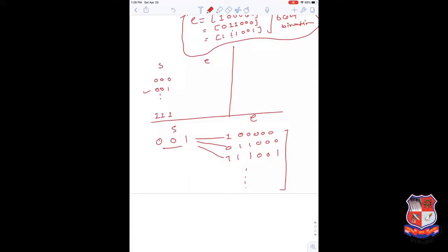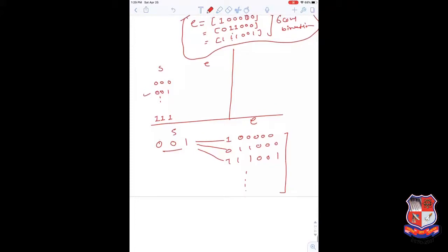If we ended with a single value of error vector, then work becomes very simple, because that error vector we have identified this way, and we can use it to get the code vector by XORing error vector E with R, or R with E, and then we are getting the code vector directly. So here we can identify the error vector, but the problem is there are multiple values. So with which value will we go? We'll apply the maximum likelihood algorithm.